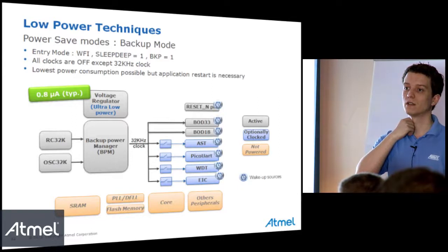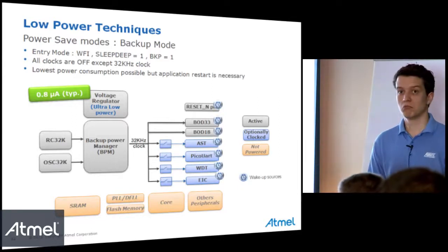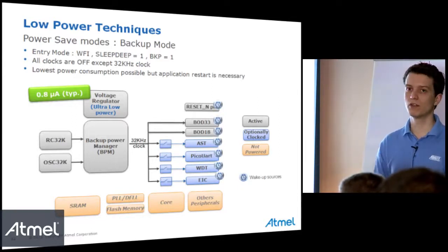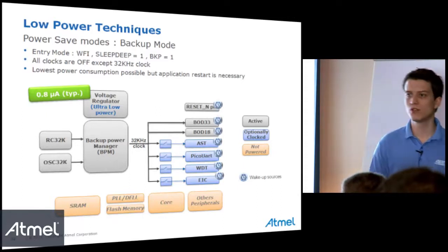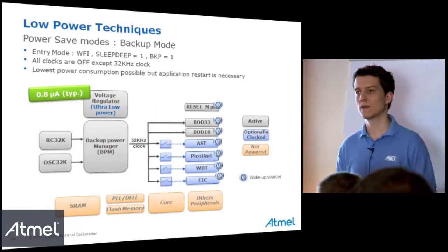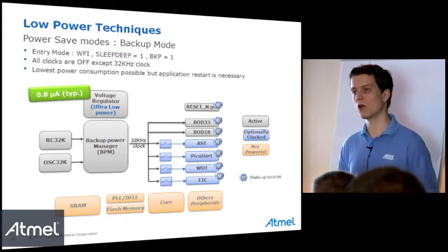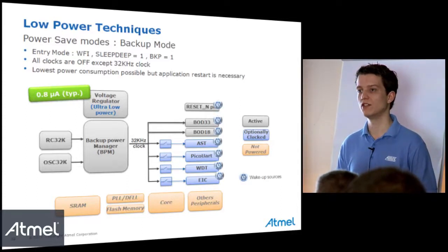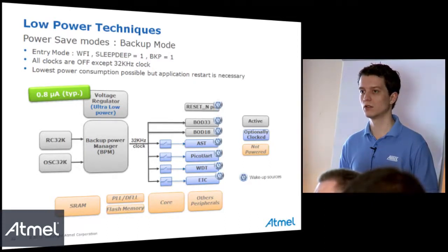And I can leave all the analog input, the LCD. For me, there is no impact. For the LCD, it depends if you want to use the LCD. So you need to keep only the VDD in. My product will stay, I don't know, 2 months on the shelf, after calibration of the RTC. Yeah, just powering the VDD in would be okay.